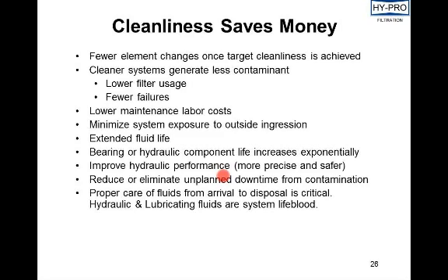To make a test stand that can handle changes in flow through the particle counters and rapidly change system flow at a 4-to-1 ratio, it's a big investment. And most of the test stands around the world are built around the ISO 16889 standard. Also, the technical committees are typically made up of filter manufacturers and large users, so it's difficult to get consensus on a new standard that would basically require everyone to buy a new test stand. So that's why we stopped trying to push it to be an ISO standard, and we just let it be our competitive advantage.